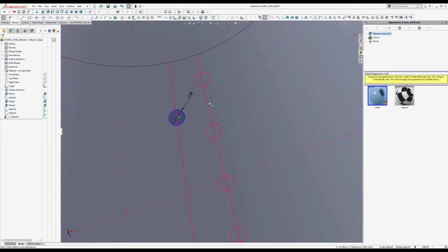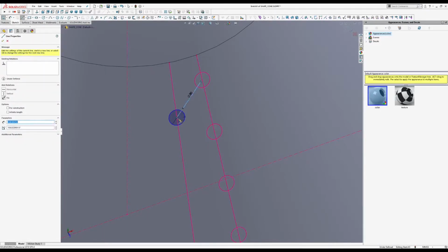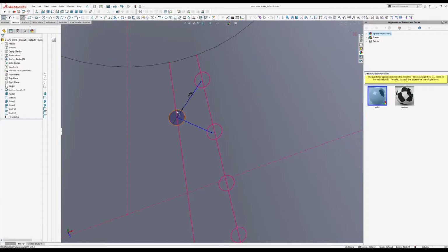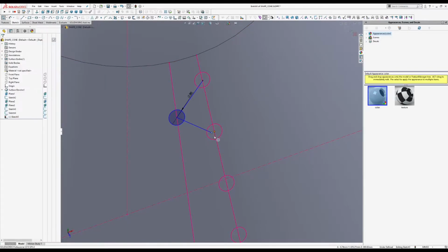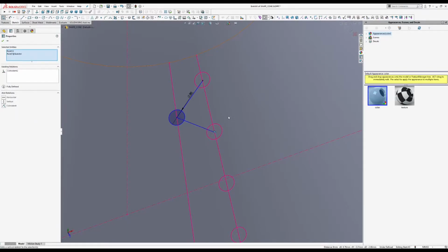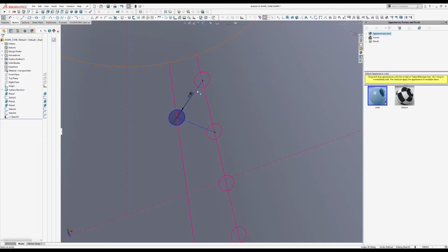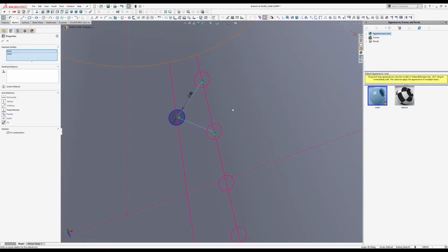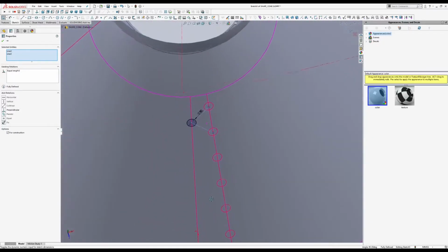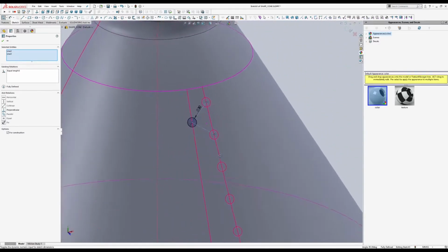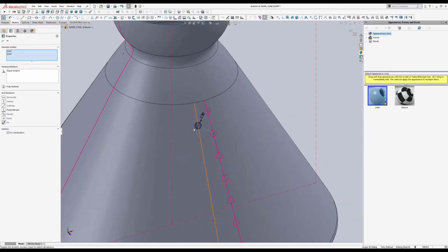What you can do now is just to make two lines, which go through this to the center of this circle, and try to connect the dots here of this line to the center of the other circles. So like this, coincident. Make these construction lines and also make them equal. You see that you are basically spacing the circle on the side of the main line.